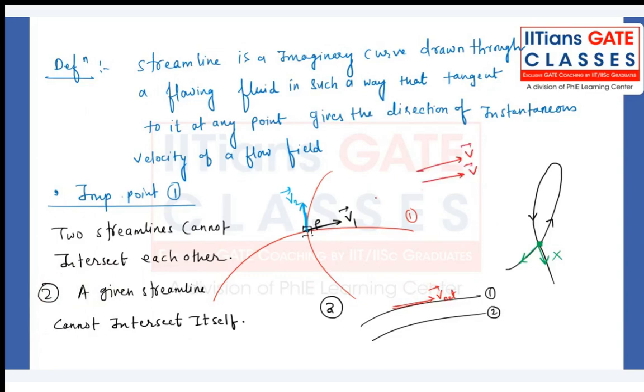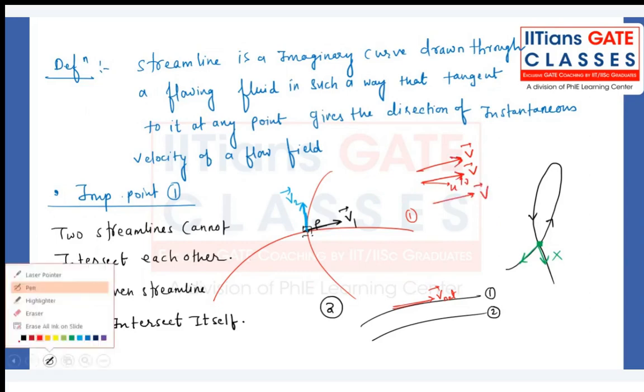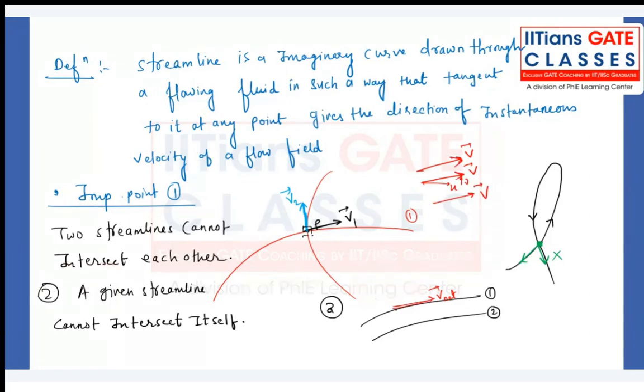You might have some u component, some v component, but finally what gives you the direction of the flow field is the net, final velocity vector. So if the velocity is in this direction, there cannot be any flow perpendicular to this streamline, or any flow across these streamlines. Note down, no flow is possible across this streamline.